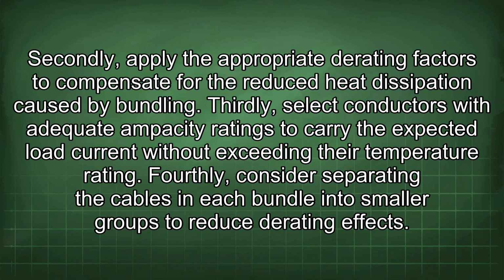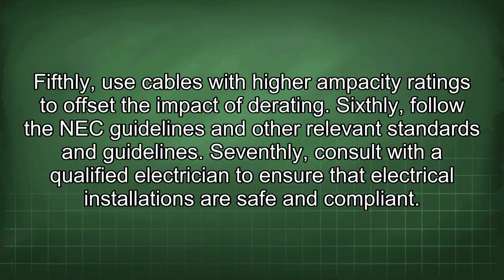Fourthly, consider separating the cables in each bundle into smaller groups to reduce derating effects. Fifthly, use cables with higher ampacity ratings to offset the impact of derating. Sixthly, follow the NEC guidelines and other relevant standards and guidelines. Seventhly, consult with a qualified electrician to ensure that electrical installations are safe and compliant.